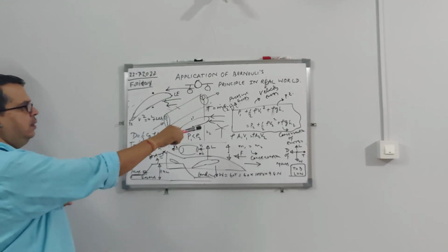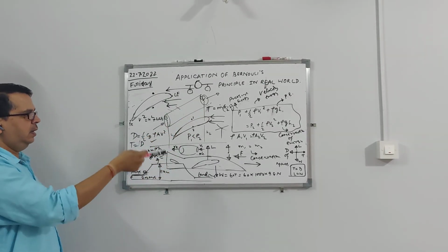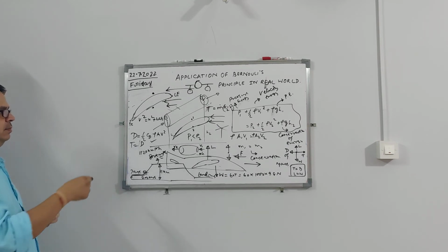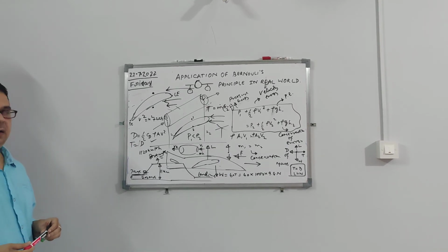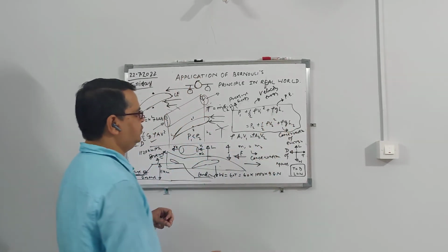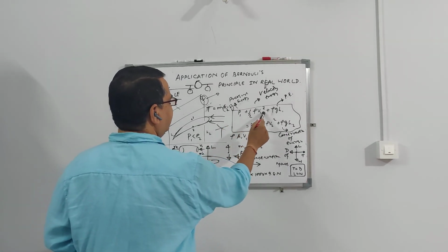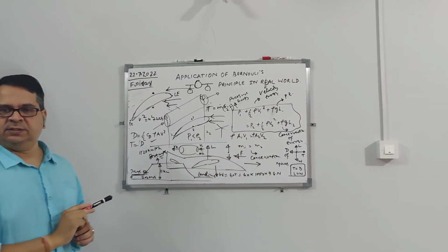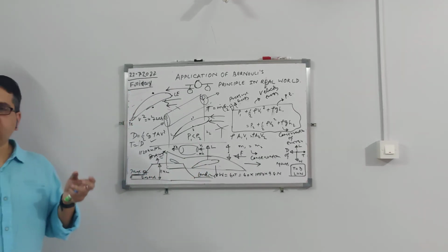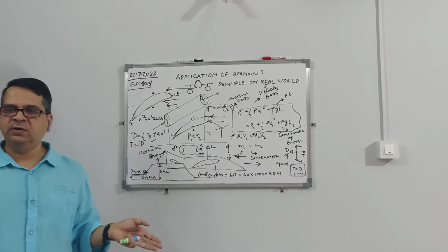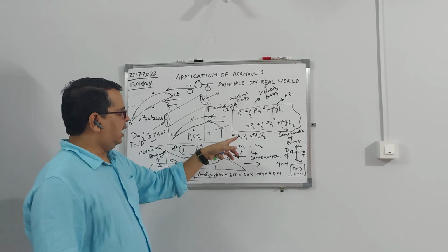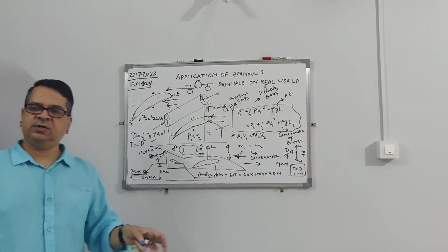Yeah, so you understood what is Bernoulli's equation and how this is being applied in aerospace applications. Okay, so here you can see, if you forget this H1 H2, that when velocity is high, the pressure is less. So here what is happening at the top, the velocity is becoming more. At the bottom, the velocity is less. That's why at the top velocity is high, that's why pressure is less. At the bottom, velocity is less, that's why pressure is high.